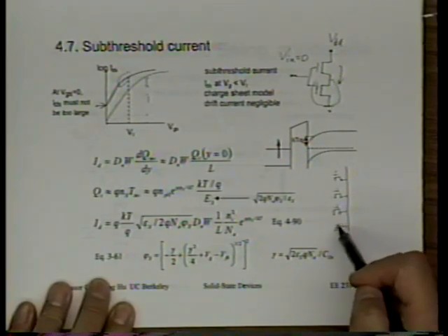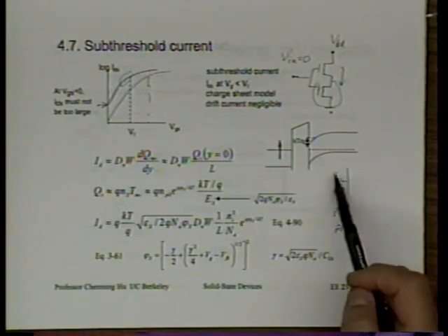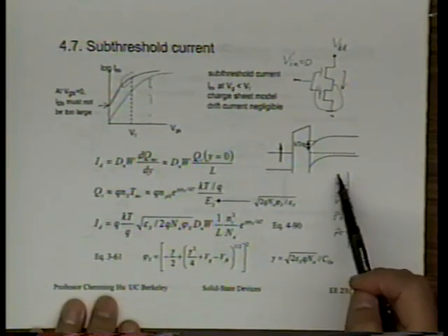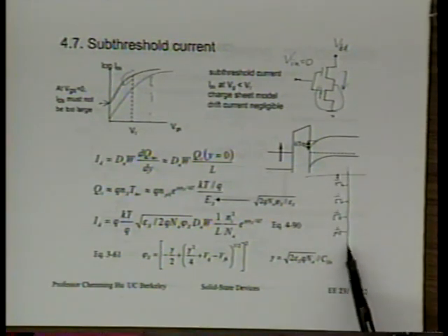When we want to sense this memory or read the memory, what we usually do is we turn on one of these rows. So turn on one of the transistors. The other transistors connected to this bit line are left in the off state.